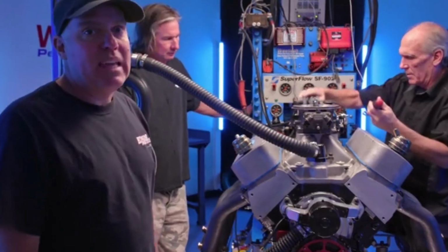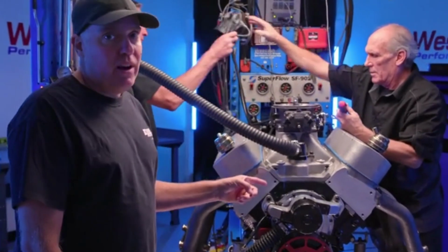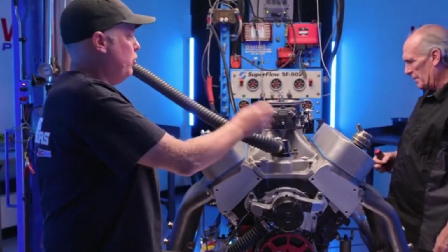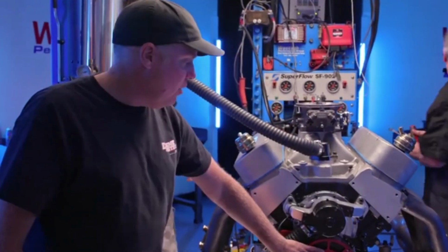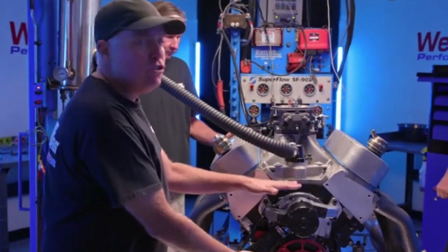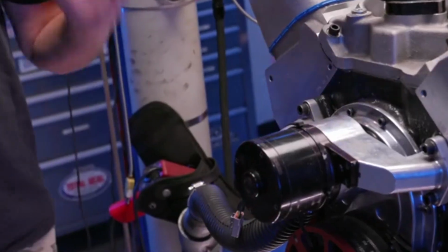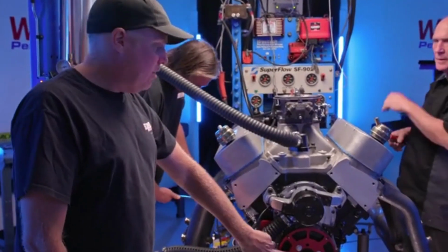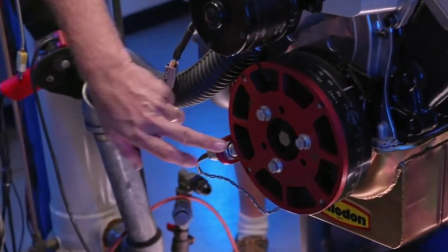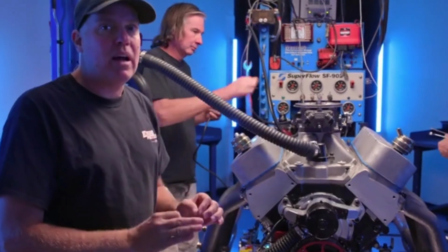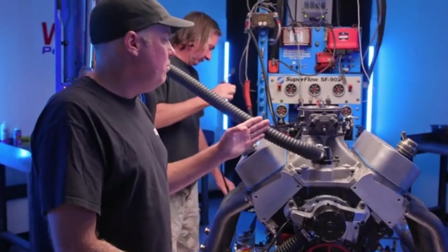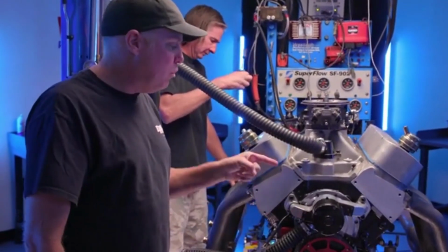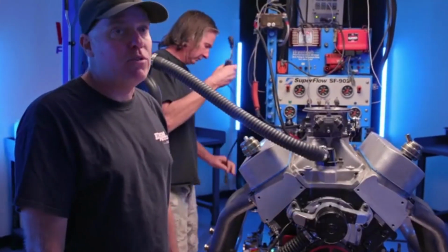And the changeover begins. We're about to swap from the long rod engine to the short rod engine. Now we're gonna use the exact same cylinder heads, intake manifold, distributor, and carburetor, and also the crank trigger on the thing. We're just gonna change the short block, which is as identical as we could possibly make it with the exception of the rod length. You can see that we've got a crank trigger ignition on this thing. That's just so we can be much more precise about the ignition timing. This thing made the same power between 34 and 38 degrees total on timing, and I'm super curious to find out if that's any different with the short rod engine.